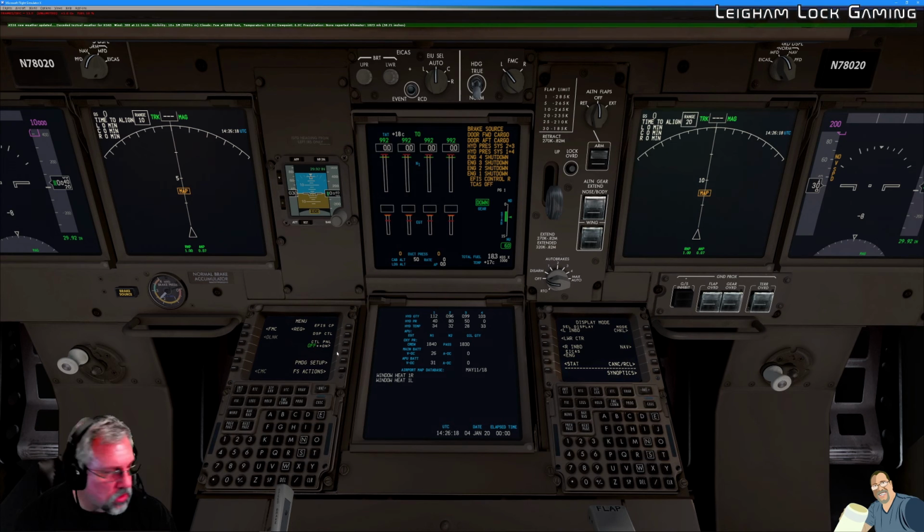We also want to take a look at the hydraulic quantity, 1112, 1, basically all almost in one, and this also is normal for most of the startups that I have in the 747 aircraft, so no problems there. Plus, just to point out that if these numbers were in a warning or a dangerous state, they would actually highlight yellow or red if there was a problem with them. So something else to look for.